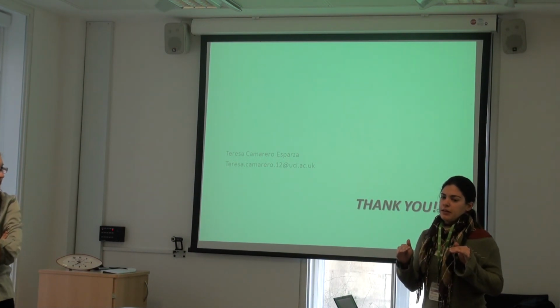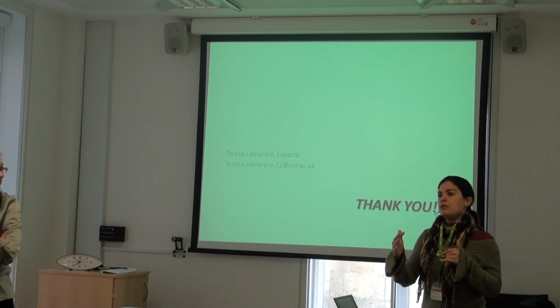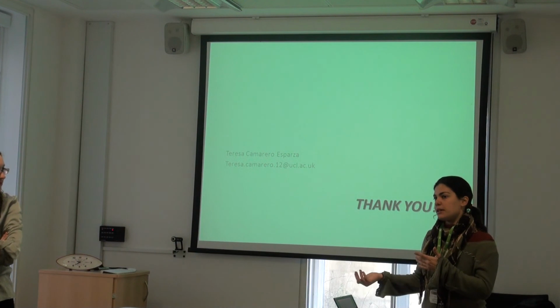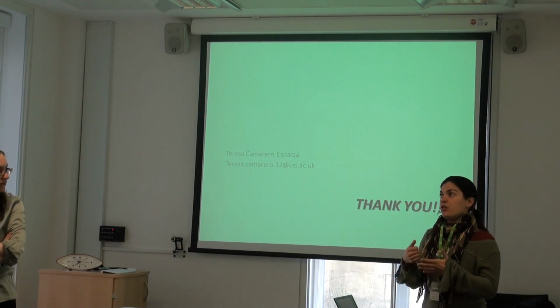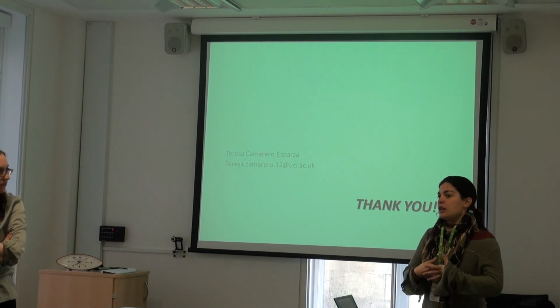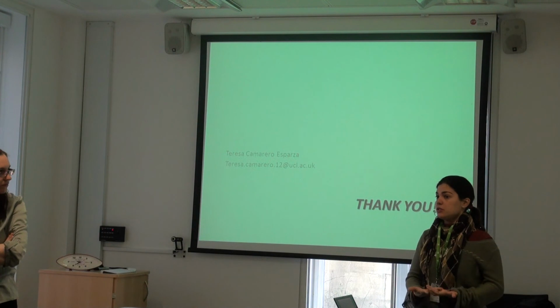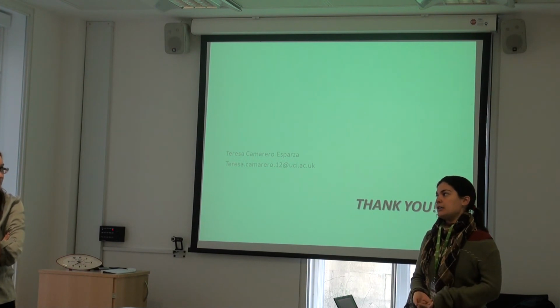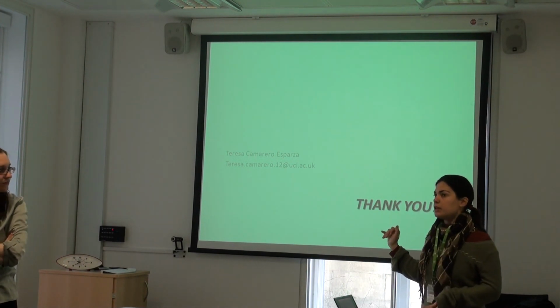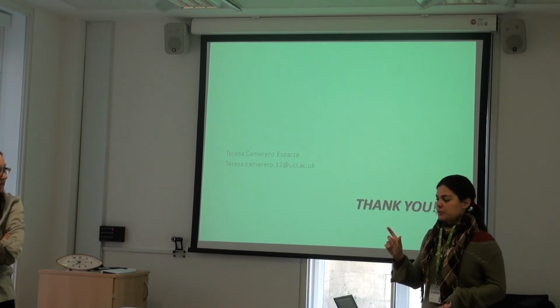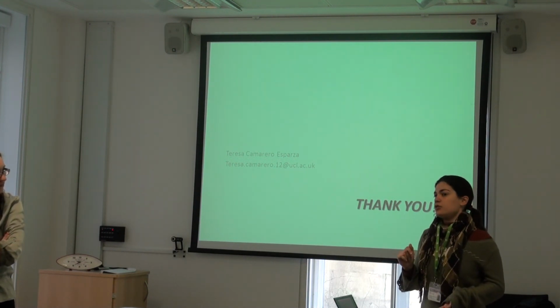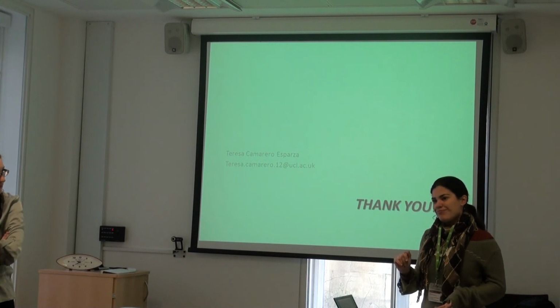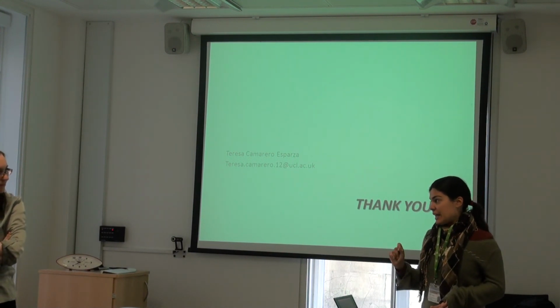So this means that the microbial community will grow better, faster, and will be more efficient in processing all the organic matter. And in the specific case of biogas production, in addition, methane is made of carbon, not of nitrogen. So really, you want to put in things rich in carbon in order to produce it. And the problem with nutrient removal that I was going to mention as well is that in the case of biological removal, to remove the phosphorus, especially to put it inside the sludge, you need to have readily biodegradable carbon as well. And sewage is not usually that good. So in the end, that is a shame.